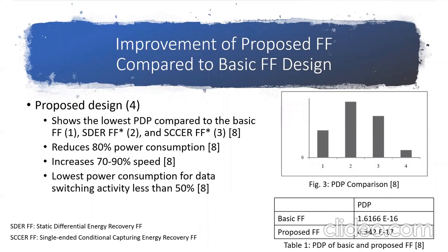The improvement of the proposed design compared to the basic flip-flop design is shown in this slide. As you can see in figure 3 and table 1, the proposed design, which is marked as 4 on the graph, shows the lowest power delay product compared to the basic flip-flop and 2 other commonly used flip-flops, which are the static differential energy recovery flip-flop and the single-ended conditional capturing energy recovery flip-flop.